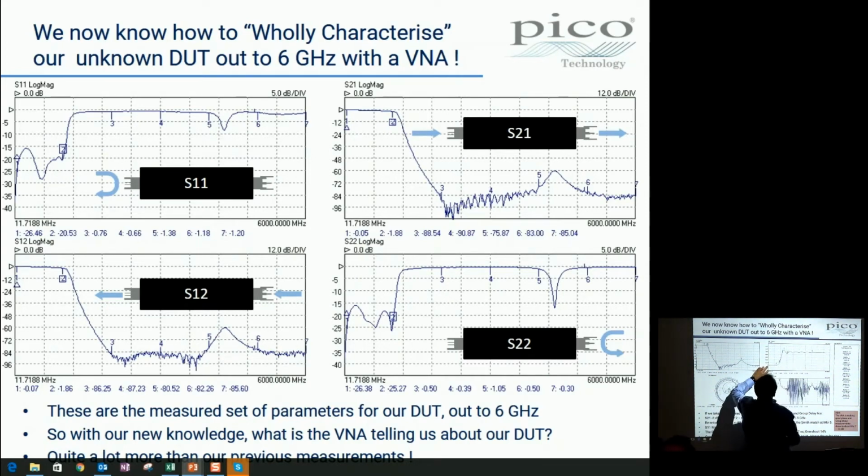It shows us the 2 nanosecond delay that we saw on our scope. We can see in the group delay the 2 nanoseconds that we expect to see for the vast majority of the frequencies going through this filter. And then we can see that as it rolls off, some of the signals down the slope get delayed further by 4 nanoseconds.